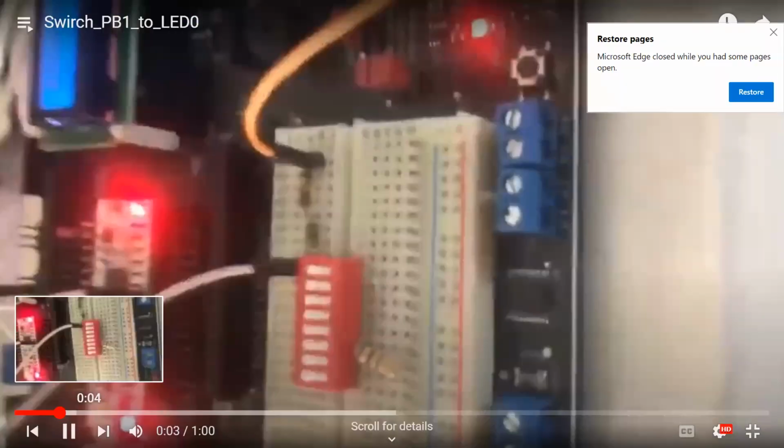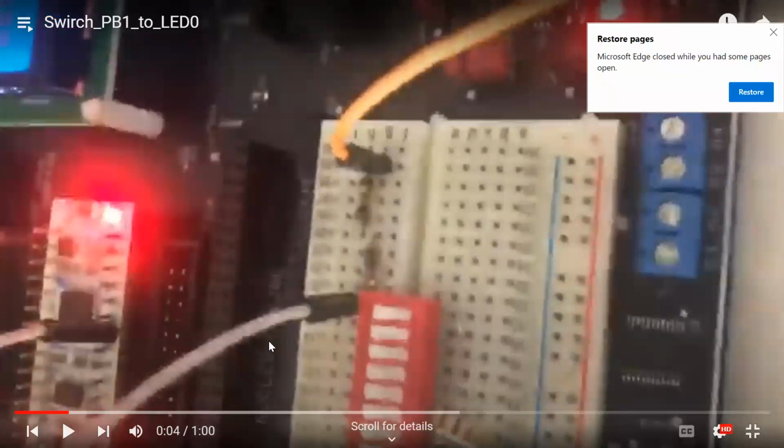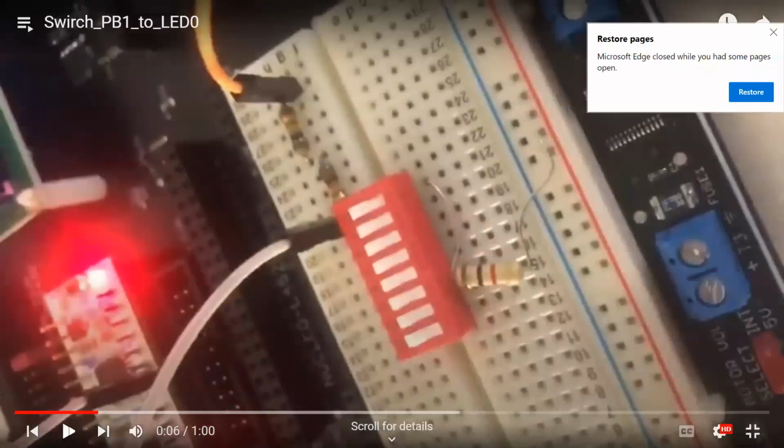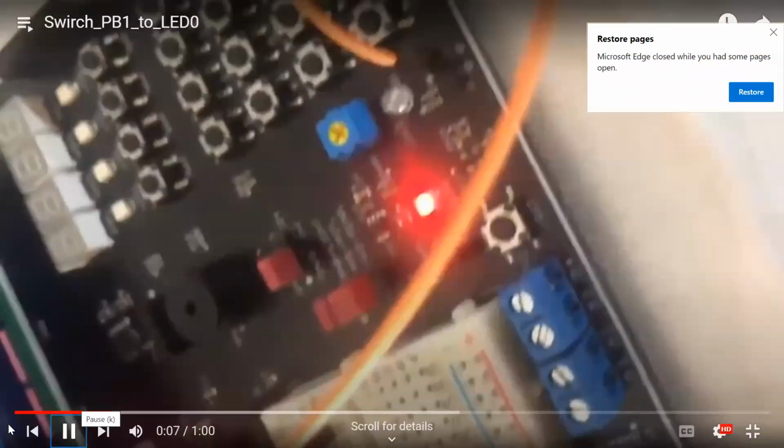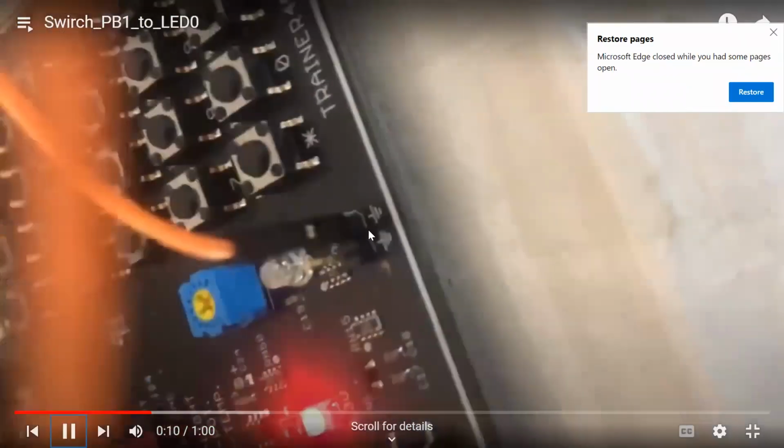As you see here, look. It's connected from here to the microcontroller. Please don't use any external power supply for the 0 volt and 5 volt. Okay, as I told you, the board already has 0 volt and 5 volt. Okay? So now you see the switch, the LED is off because the switch is in one position. In the other position, yeah, look here, I'm showing you, this is the ground, okay?